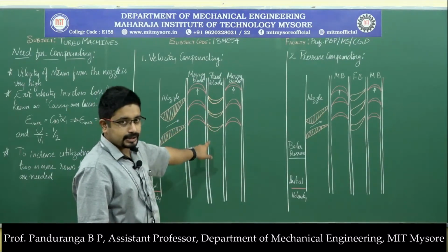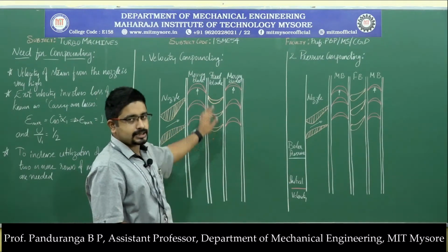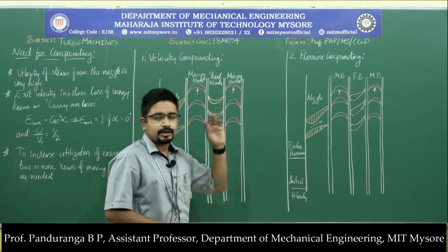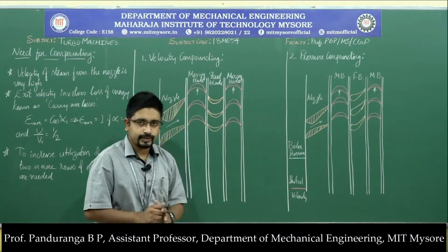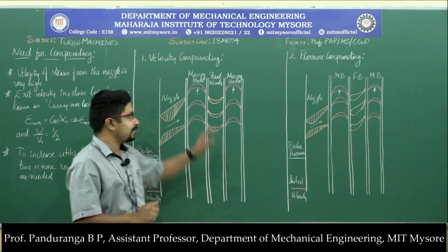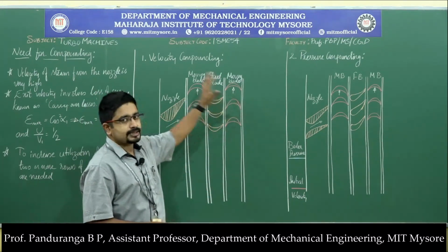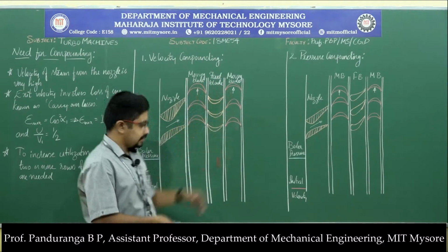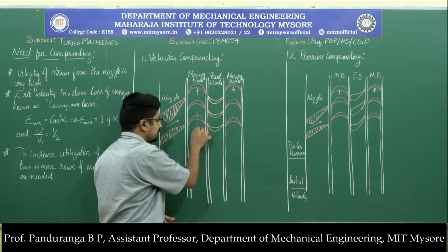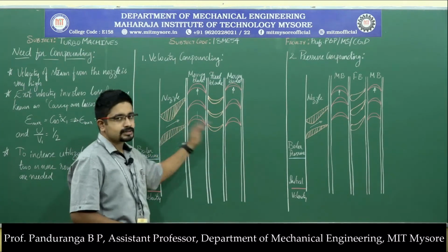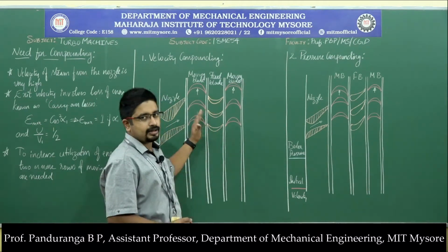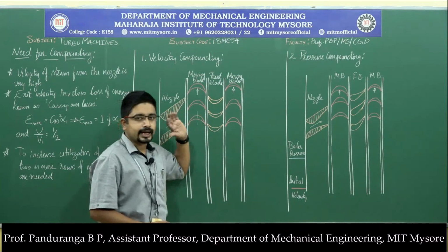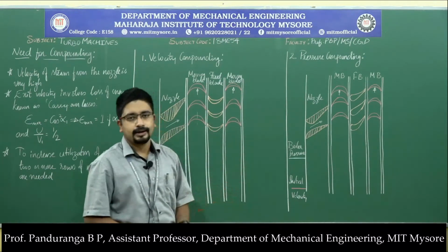Again this is an impulse turbine. So energy exchange happens in the moving blade, the energy which is in the form of kinetic energy only. So only the kinetic energy will be absorbed by the moving blade, and you can see that the blades are symmetric. If I cut this blade here, then the blade is symmetric over the central axis. So these are the blades where only the kinetic energy of the fluid will be absorbed.